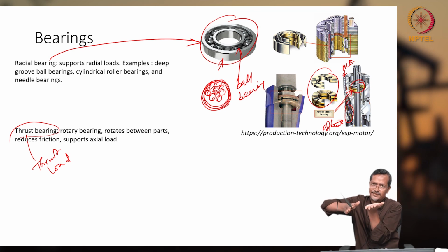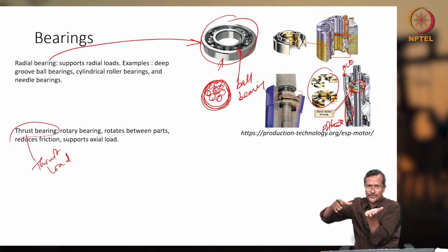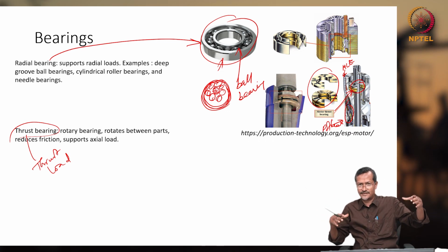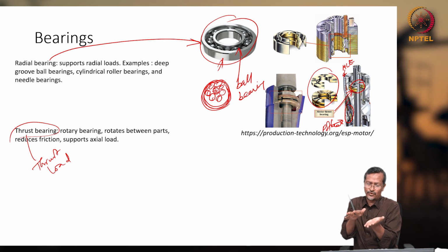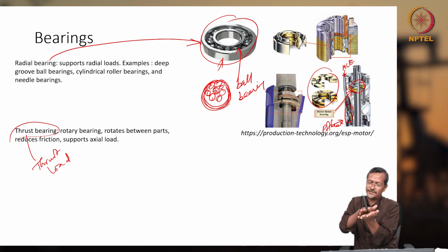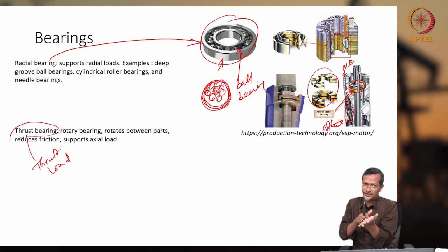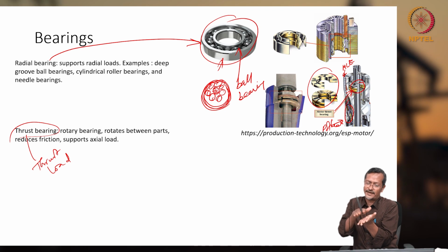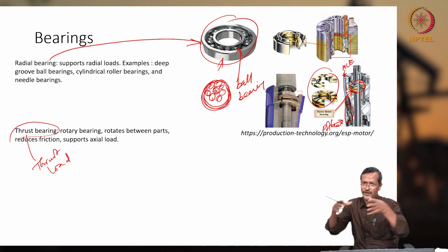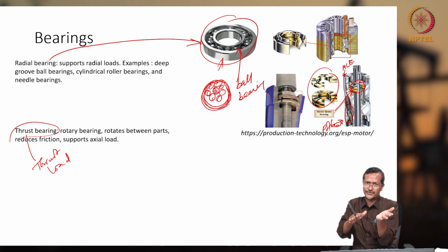So this surface will be holding this vertical load, whatever is there, and this will be fixed on your outer casing, right? So the whole load will be going to this one. This is giving load, but this is not taking any torque. This is taking only axial load. So this will take axial load and transfer it to your outer casing, and the shaft will be rotating, and all the axial force will be transferred to this one.